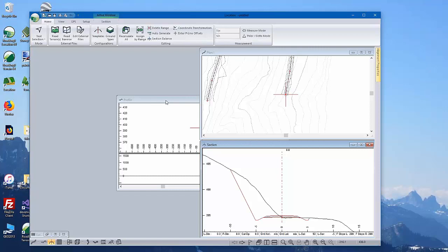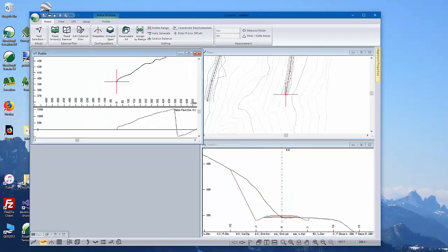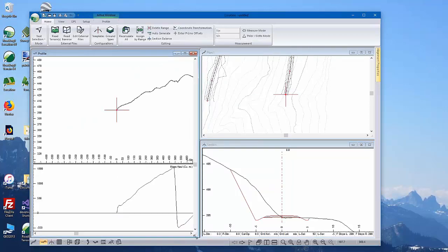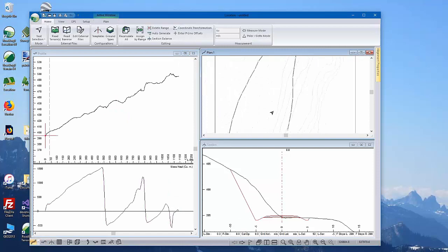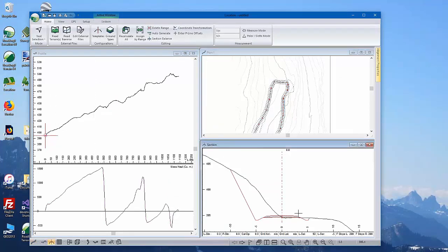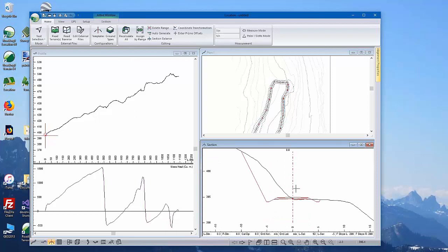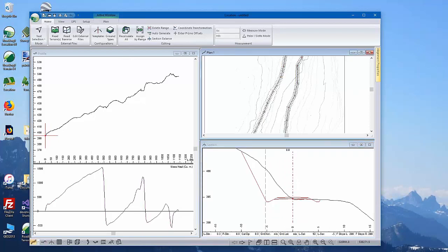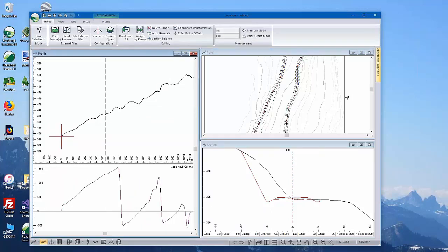And there you go. We've got the usual road scenario: plan, profile, cross section. So we've got a typical low volume road template set as the default, and because I put in a P-line, I've actually got a starting alignment that runs along the P-line, and there's my profile, which is following basically just the ground. That's the default. I haven't got a profile.